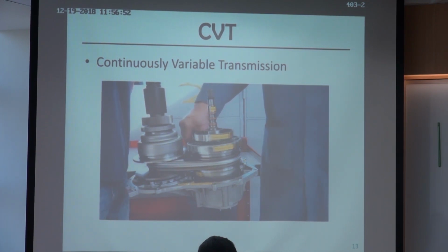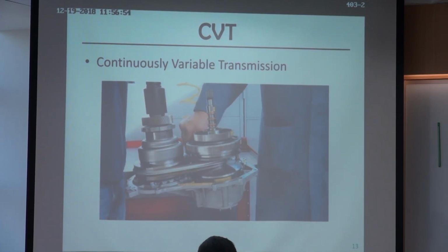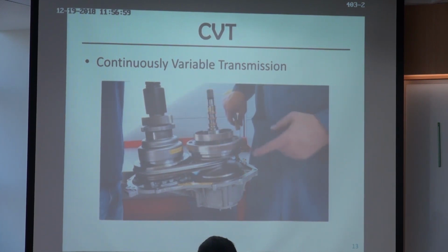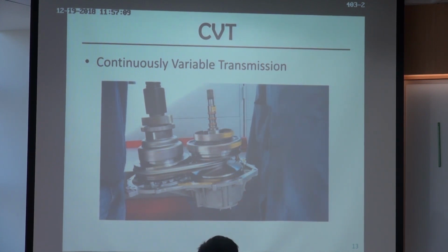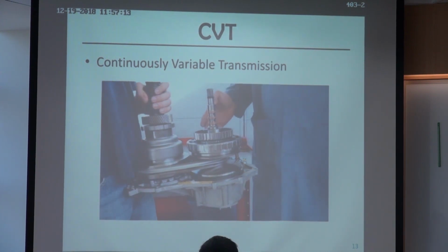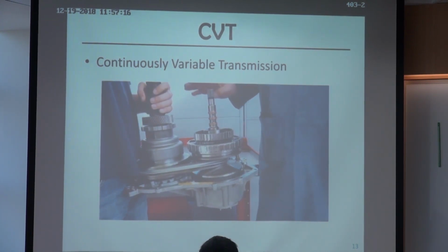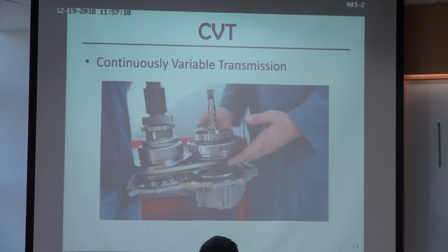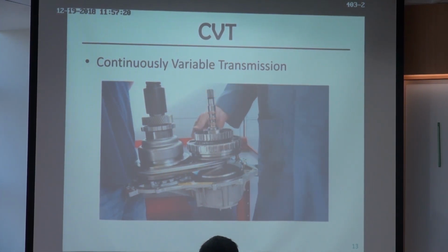For the previous example, the manual transmission, we also have some fixed speed ratios. But for this one, we can have a continuous speed ratio. I can change the distance with a very tiny difference and slightly change the ratio. Yeah, so that's it. It's similar to a gear train, but just uses a different mechanism to achieve the speed ratio.